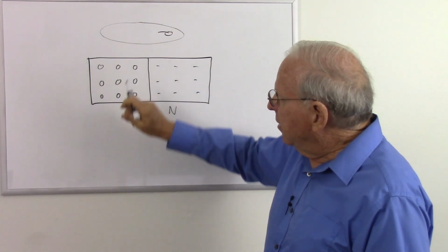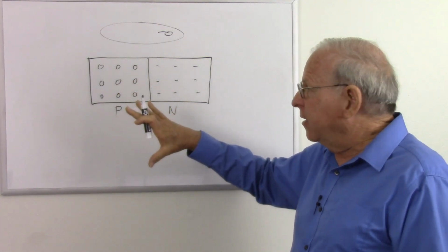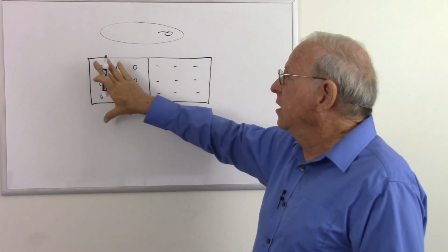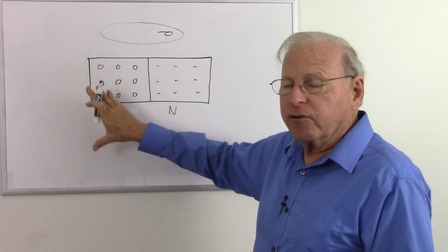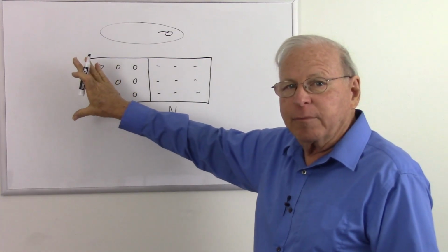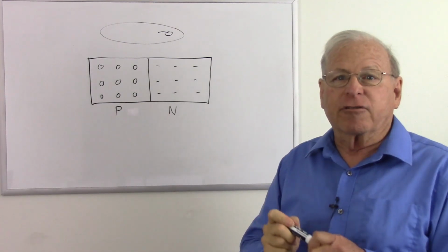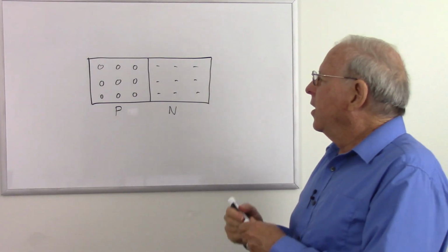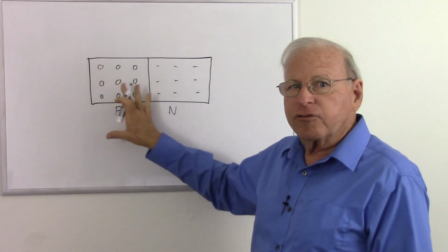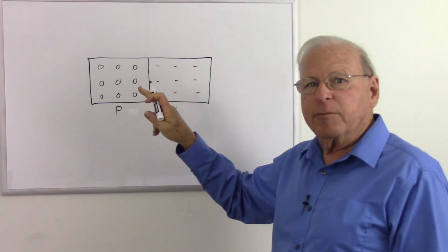When analyzing p-type material that has fewer electrons than expected, it's actually easier to follow the holes than to follow the electrons. So we consider the holes to be charge carriers over here. They carry a positive charge. So we have holes as charge carriers that can move electricity, and over here we have electrons as charge carriers that can move electricity. So we have the stage set: electrons as charge carriers over here and holes as charge carriers over here. And remember, these holes are very attractive to electrons, and these electrons are free to move around.